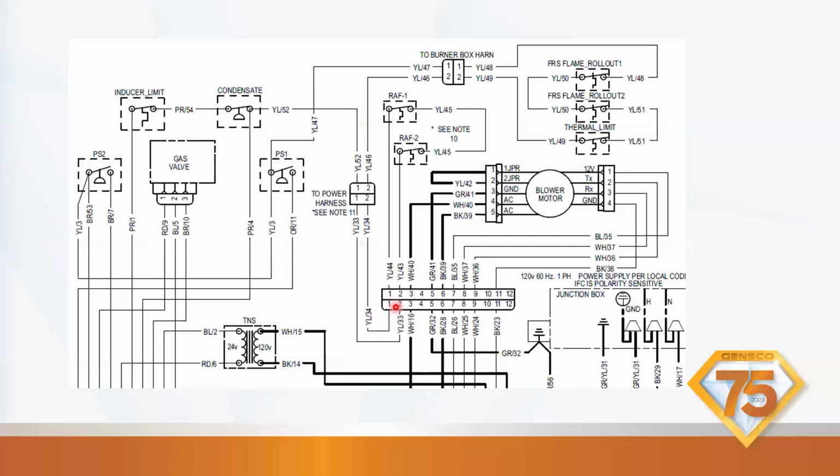It gives you a lot, and you don't even need to go to this plug. If you look, right, you can go back to this plug right here. And so you can measure from this plug, these two yellow wires. You can ohm from there. You can check your AC voltage there. You don't need to go into the limit.